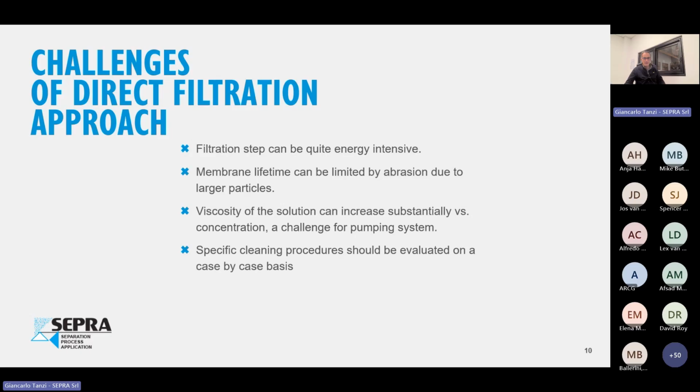Even if the water media is good quality, if you do not input energy in the process, you will anyway quickly form a dynamic layer on the membrane, and the permeability will drop dramatically. So finally, you need to recirculate. We have seen that backwash may help in this application, but backwash alone is not enough.